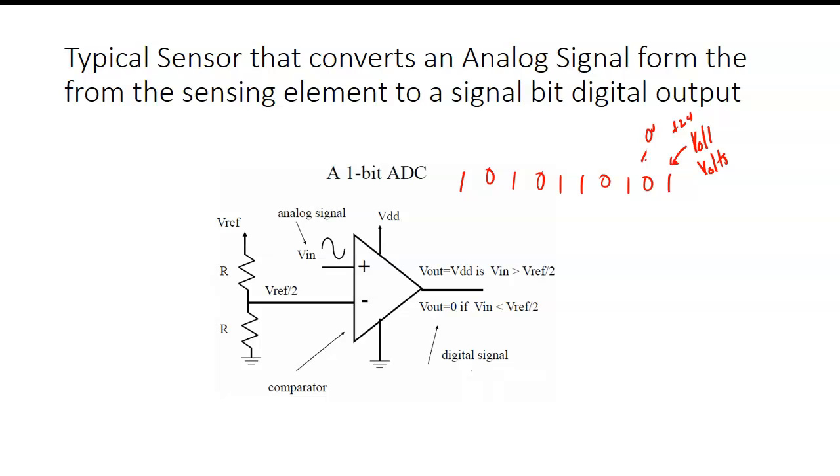We're just dealing with is the voltage there, is the voltage not there. And like I said, with a PLC, we're using plus 24 volts, and it'll recognize anything above 20 volts as a legal one. So now we've got a 4-volt margin that our sensor could be within, and still be able to recognize that as a true output.